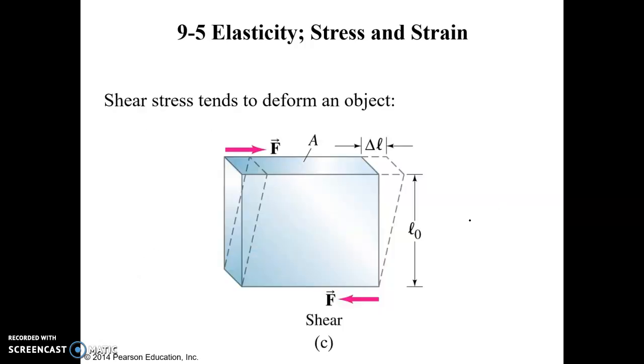Now, shear stress. What shear stress means is shearing occurs when you have a plane, a shear plane, like the bottom of this rectangular cube, and the opposing forces, this force down here and this force up here, this force couple, rather than acting perpendicular to the plane as they did with tension and compression, they're acting parallel to this plane now.